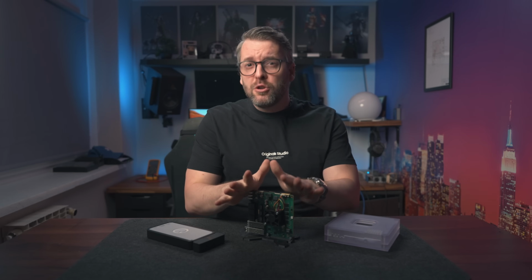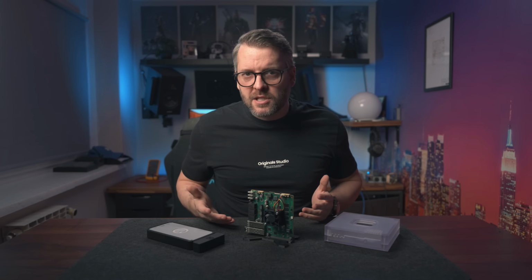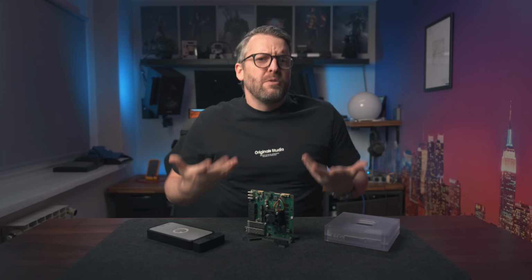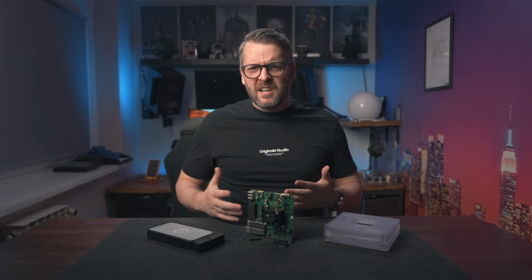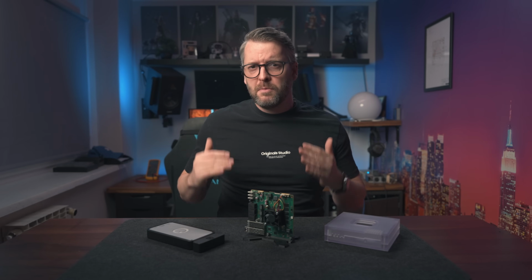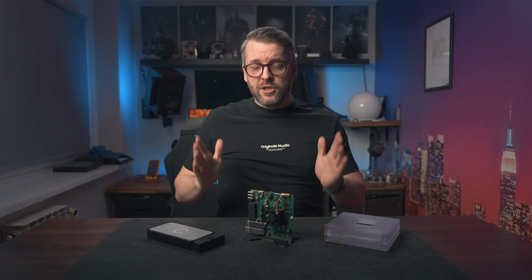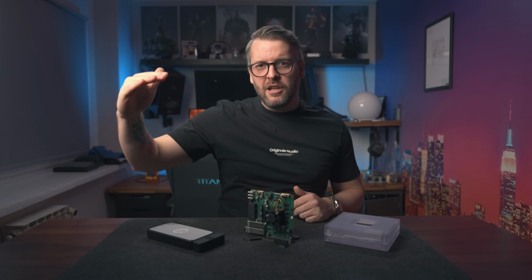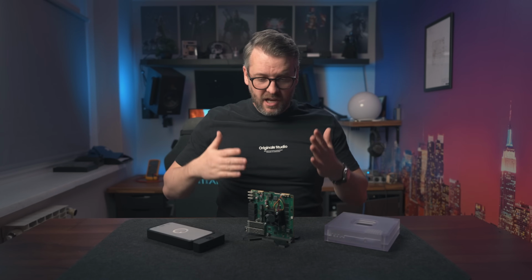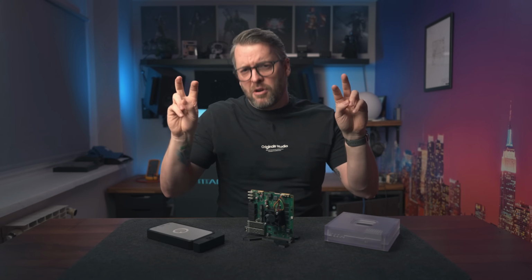Now, before we move on, a question that's worth answering is, why did it work then? As in, why could we boot into Linux despite the fact that we've had a couple of bits swapped in our layout? Well, because RAM is a fairly stupid device. Think of each chip as a rack of drawers. The rack doesn't really care which drawers you put stuff in, as in organizationally, as long as you put stuff labeled A into drawer for the stuff labeled B. And if you do it consistently, 100% of the time, then you'll never get confused or have things corrupted, right?